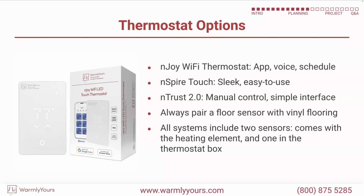Always pair with the floor sensor. So these thermostats come with a floor sensor, as mentioned. We mentioned earlier as well, your heating element will come with one. Put both your sensors into the floor, but only connect one at a time.